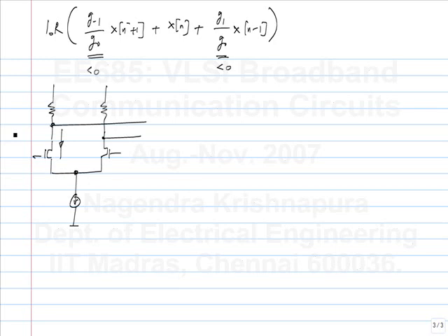No, this is the output signal. What should the tail current be? The total tail current that flows through this, not just through the one differential pair, whether you realize it as one differential pair or many differential pairs, what should it be? That current cannot be, the current going in this direction cannot be less than 0, right? So what is the total current that is drawn at a minimum?